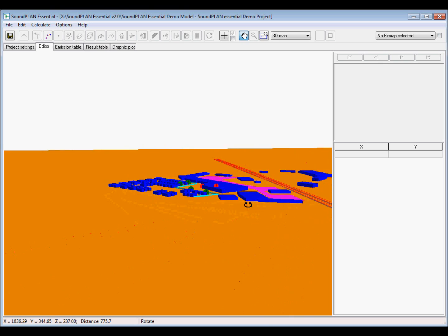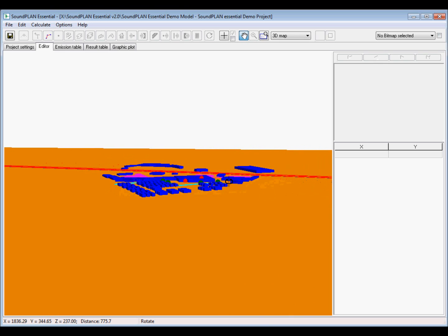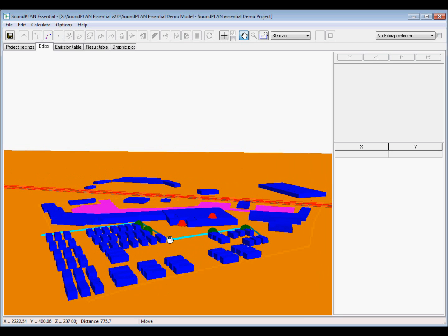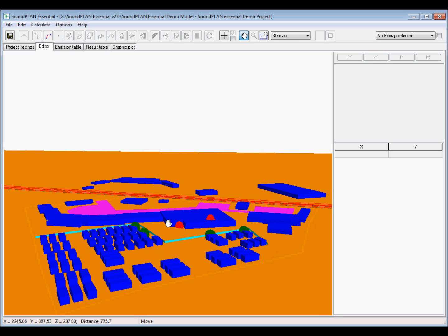The red dots are representing sources, in this case point sources. The purple area in the background is the parking lot, and the red lines in the background are the road source at different elevations. You can actually see 3 lines for each lane, and that represents, for the TNM model, the 3 sources. Let me turn that back to sitemap.